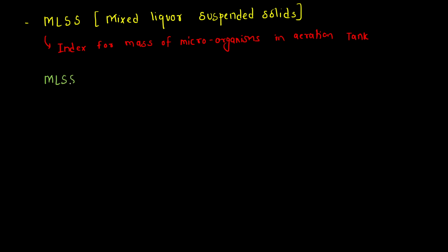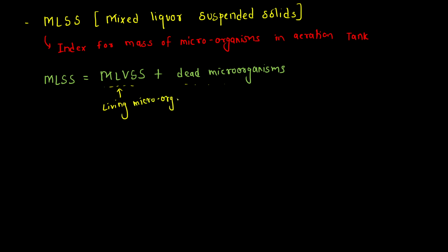This MLSS is equal to MLVSS plus dead microorganisms. So when we are saying MLSS, this MLSS contains both MLVSS and dead microorganisms. Now what is this MLVSS? This MLVSS means living microorganisms, and it stands for mixed liquor volatile suspended solids, where V stands for volatile.